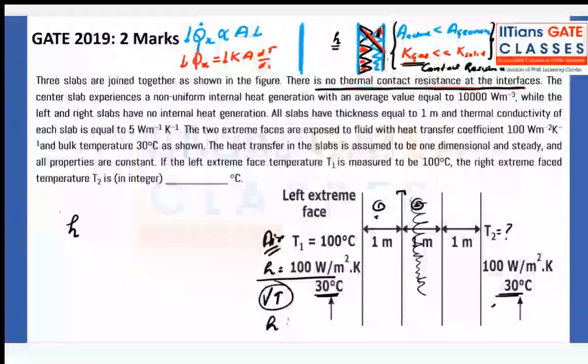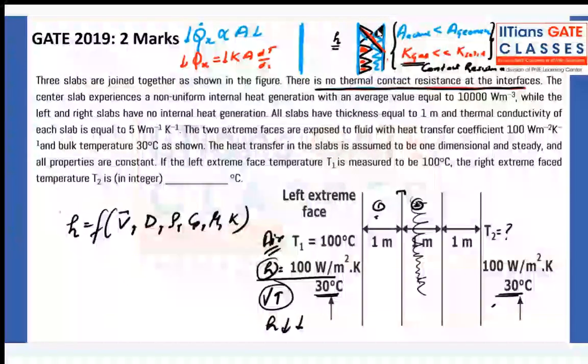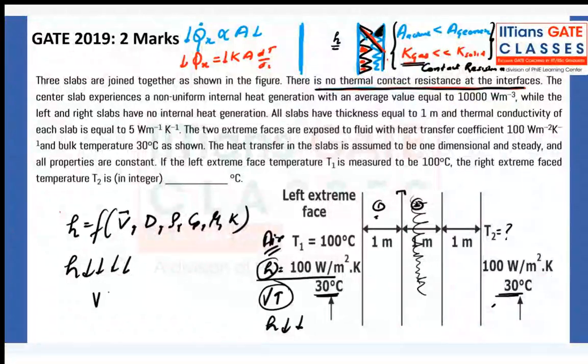I told you h is a function of velocity, characteristic dimension, density, Cp, viscosity, conductivity, so many things. So you cannot take this h and calculate heat transfer here, and anyway the velocity will be almost zero if the air is trapped in these voids. If the velocity is almost zero, it will have very, very low heat transfer anyway. Higher the velocity, higher will be the heat transfer coefficient. Clear?